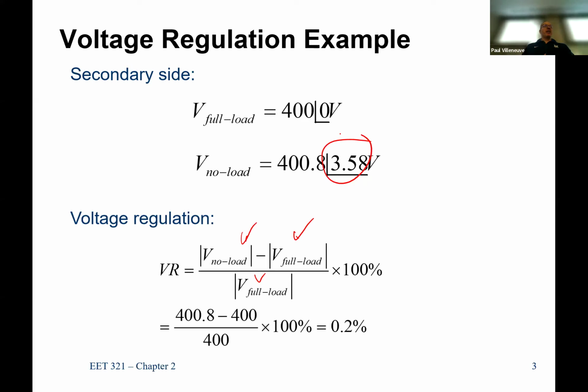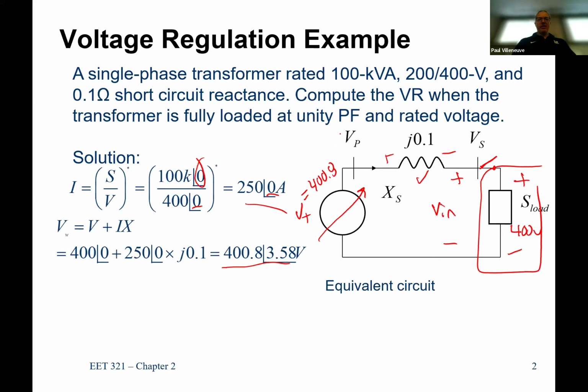And the reason why you have an angle change is, remember, this is an inductor. So the load only has P, but this has P plus jQ, right? Because it has an angle associated with it. So it's not unity power factor anymore. So where does the P go into the system? Where does the Q go? Doesn't go to the load.